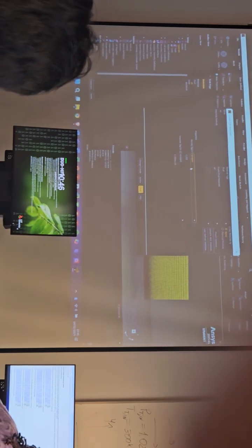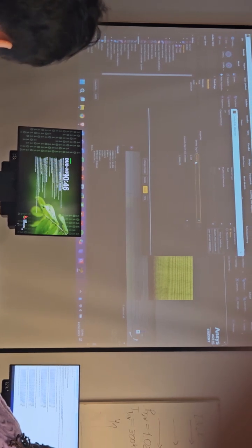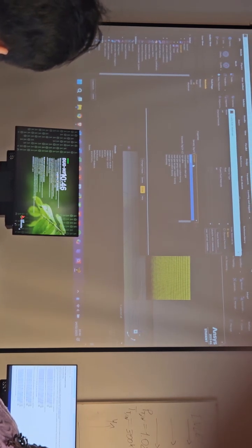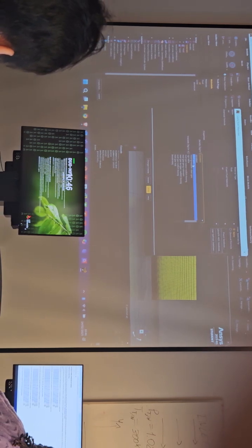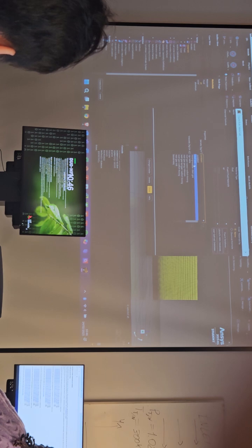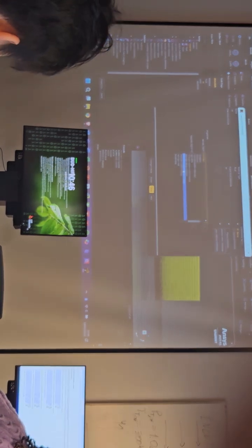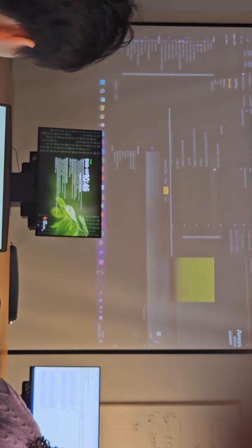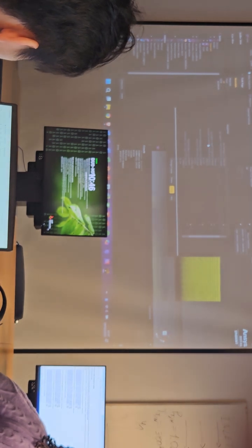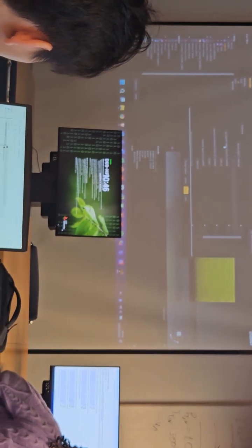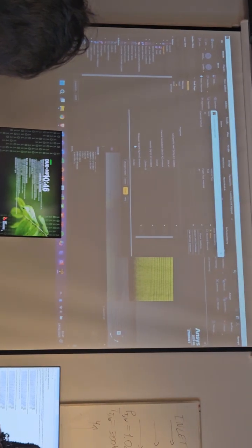What I typically do is, if you click on density options, instead of constant, I set it like an ideal gas. So I'm solving the equation of state for an ideal gas in a way that the density is a function of pressure and temperature. When I do that, you can see that now there are also other properties that are appearing, like CP, thermal conductivity, molecular weight as well.